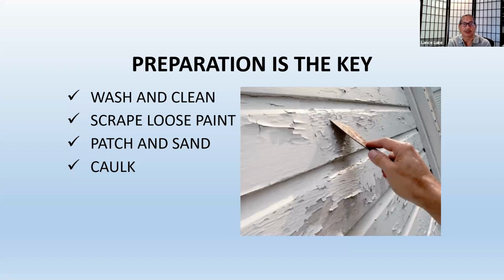And basically, sandpaper, the coarse grit is 40 to 50, the medium is 60 to 100. Then you go rougher. And then if you want to go finer, there's 120 to 220. Very fine, super fine is 240 up to 600 grit.